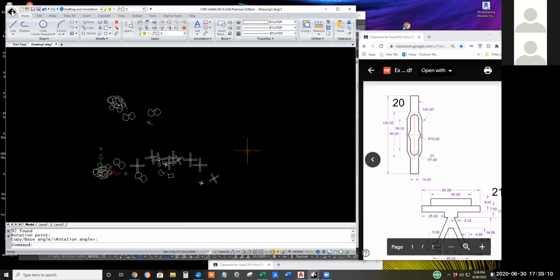When you save your DWG, it overrides the former .BAK file with the current state of your drawing and renames. Anyway, it kind of flip-flops back and forth so that in theory, you save it as it is, and you've also got a BAK file of the save you did 10 minutes earlier. They flip-flop back and forth to minimize computer time and computations, I think.